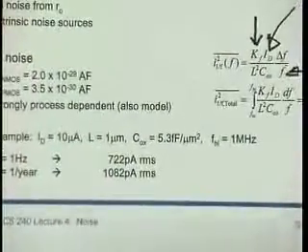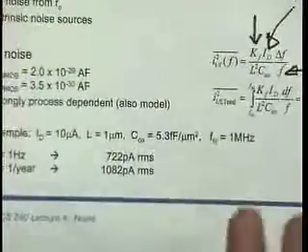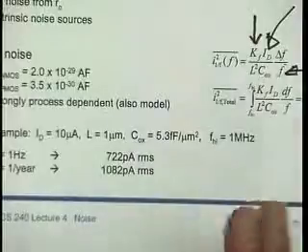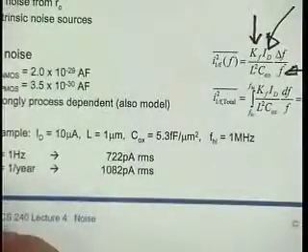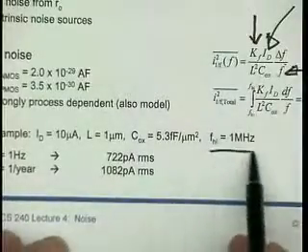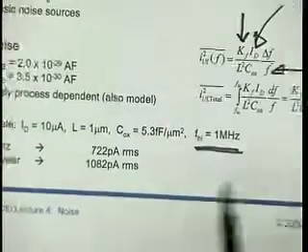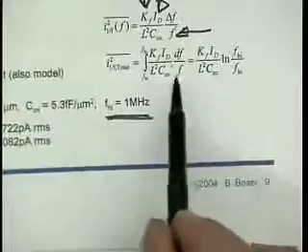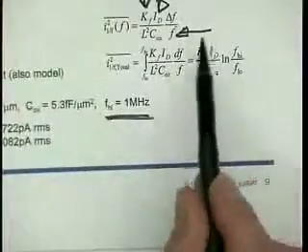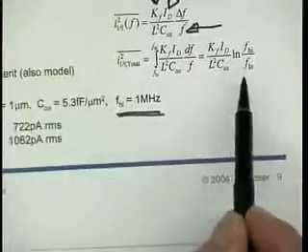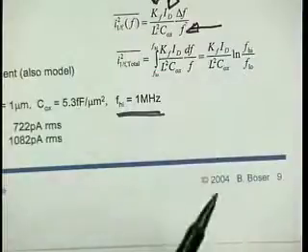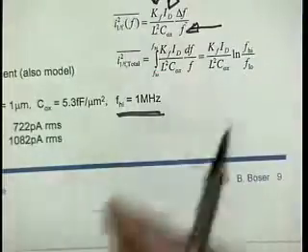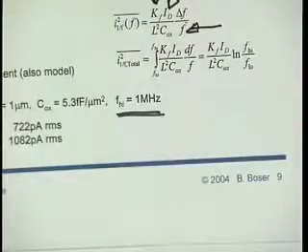Well, making a little example here, I calculate the entire flicker noise from a lower frequency, f low, to a higher frequency of 1 megahertz. Basically I integrate this equation, and I get this for the integral. And of course, if I make f low, the lower integration bound, 0, this thing blows up, and I get an infinite amount of noise.